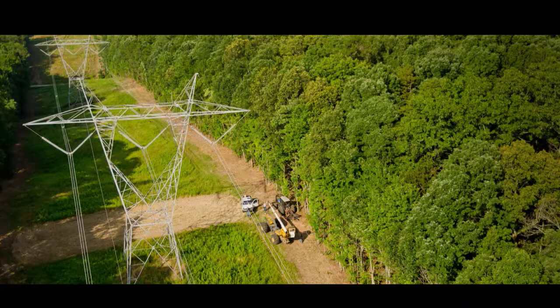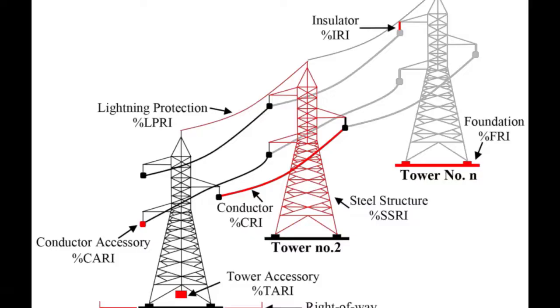Now we'll talk about the long transmission line. A long transmission line is classified as a transmission line with a length of more than 250 km or 150 miles, and a voltage level of about 133 kV and above. Its line constants are considered as distributed over the length of the line. The performance of a transmission line depends on the parameters of the line.